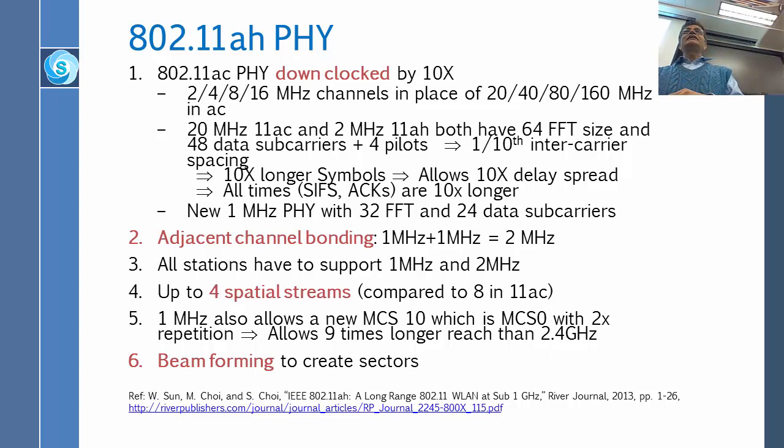5.8 had minus 70 dB from the same router, and 2.4 had much higher power. Actually, it was like minus 60 dB, 10 dBs more. Okay? So that is the thing, is that 2.4 reaches much farther, and maybe even my neighbor can probably listen to 2.4. Okay? 5.8 they cannot. However, there was another interesting fact, and that was that 2.4, even though it had higher power, had higher interference, which was not showing in that number. And so when I did the data rate measurement, 5.8 was much faster. Okay, with a lower signal, but there is a lower noise.